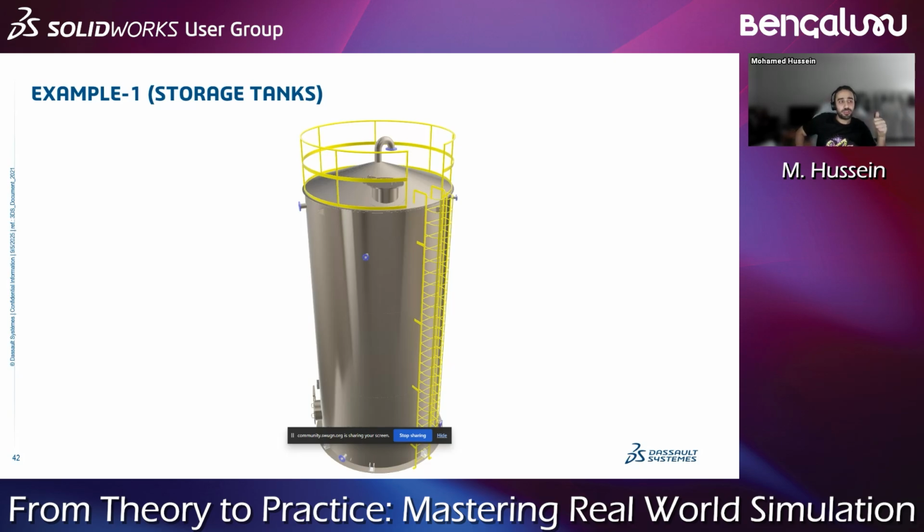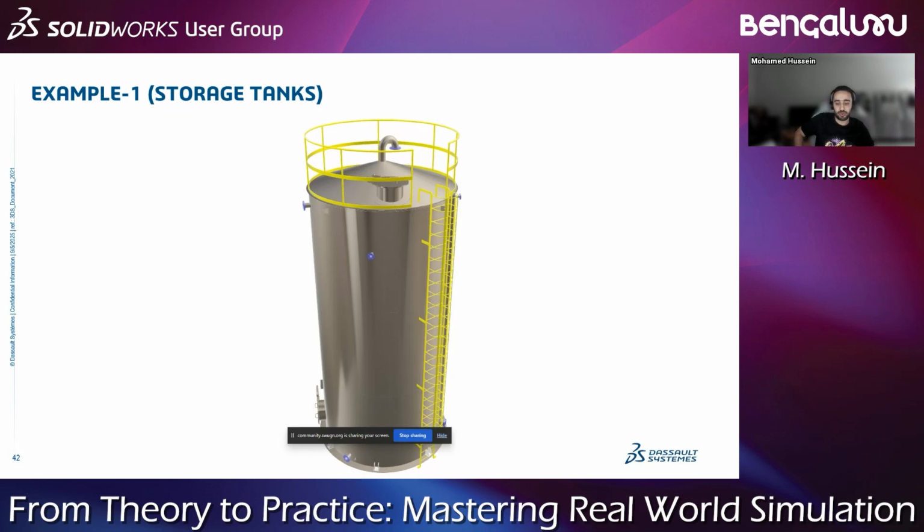The most commonly used worldwide is the API 650 standard. There is another European standard called EN 14015, and another standard called AWWA. There are a lot of standards, so you have to choose which one you use, and sometimes it's not your own choice; it is according to your project specifications.